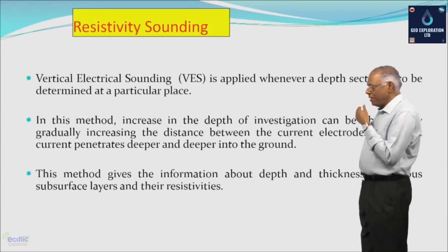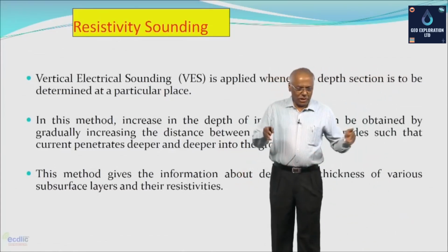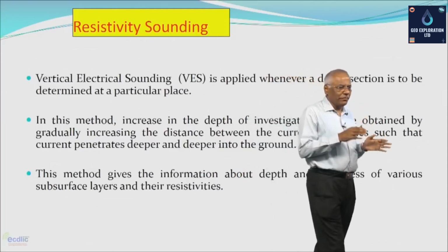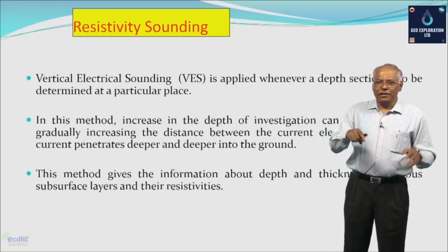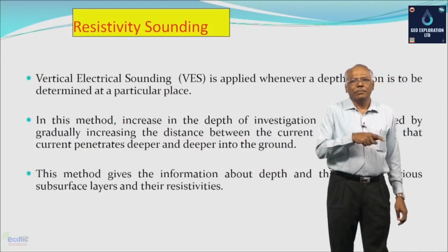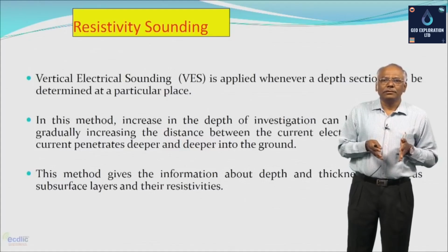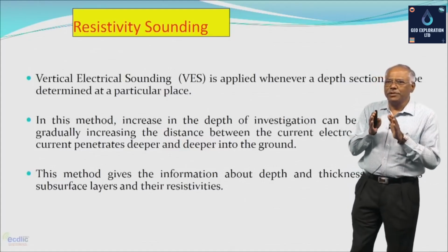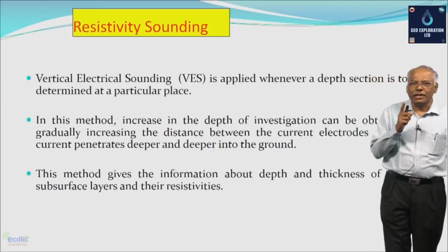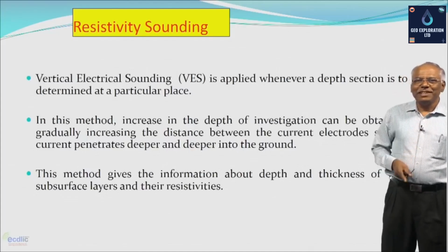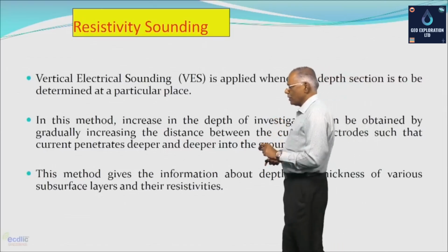Now, besides horizontal profiling, once you have the resistivity low identified in a given area, you have scanned the whole area by grid pattern and contoured that data, so you know where exactly the resistivity low is. The resistivity low is your target area from the point of view of vertical electrical sounding, and now we have to see the importance of resistivity sounding in terms of locating the groundwater resource.